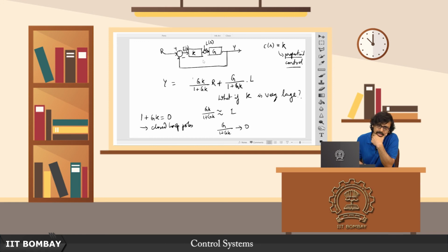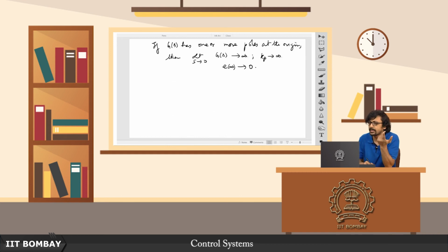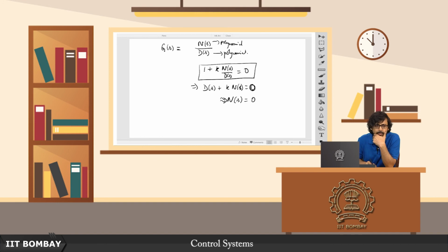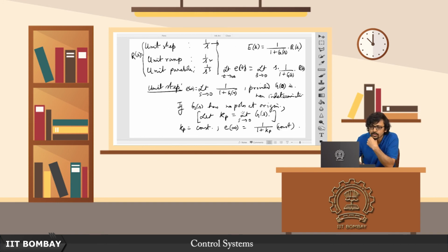But now if you use an integrator here, of course the stability might still be an issue, but in general it turns out that now you can kill off this steady state error, and maybe there is hope that you can also address the stability issue. So now we have answered this question for the step input. Hopefully we have understood this well enough to now be able to deduce what happens to this steady state error to a step input.